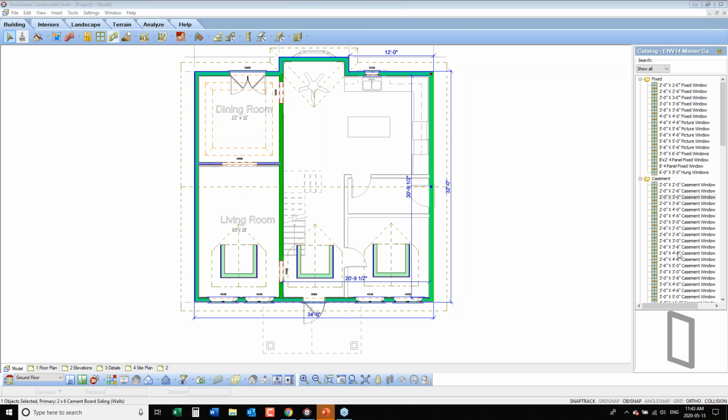Let me just go back to my page. How would I send the plan information to my manual truss manufacturer? If you have a manufacturer of trusses, we can export the file format, and it depends on what file format they're using. If I take this entire plan and I export it out, and I'll use MiTek as an example, we'll send this out in the MXF file format that MiTek will receive it in. What they do is they look at the shape of the roof. They'll take that 3D geometry that's part of this plan that we've created, and they'll automatically use that to place the trusses in it. So it gets sent out as that MXF file.